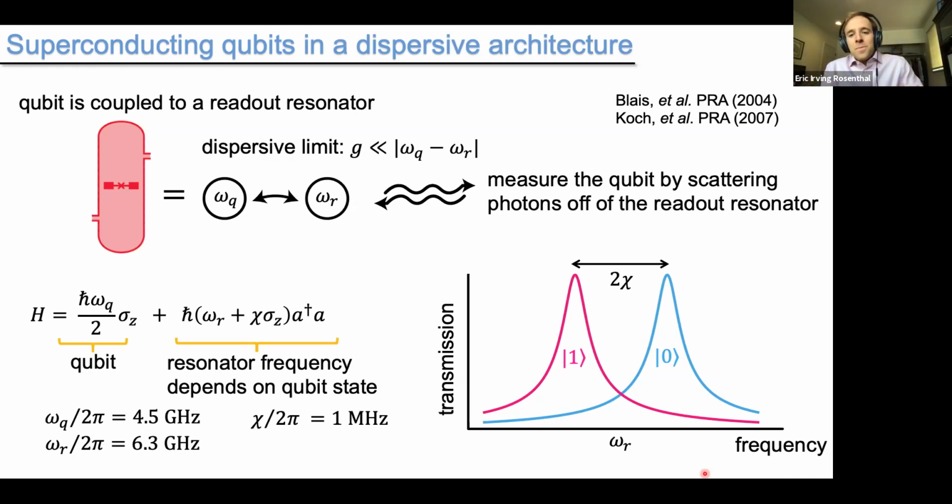But the catch is that this pulse typically contains only a few microwave photons. Too many photons and our model breaks down. And this is extremely weak by the standard of any conventional electronics. We have to have about 100 dB of amplification between this qubit cavity system and our digitizer at room temperature. And so our problem of qubit measurement has really been mapped onto how well we can measure this weak pulse.